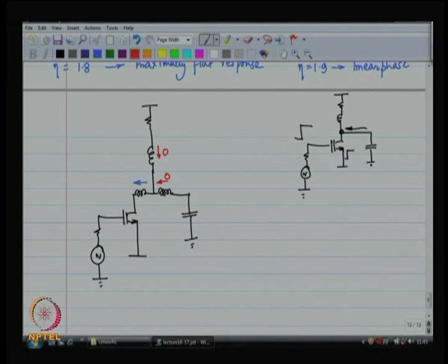Okay. And then when the current starts flowing through the second inductor, which one is it going to choose? Is it going to choose to come through the inductor capacitor series or inductor resistor series? It is going to choose to come through the inductor capacitor series, because at the right frequency the inductor and the capacitor together look like a short circuit.